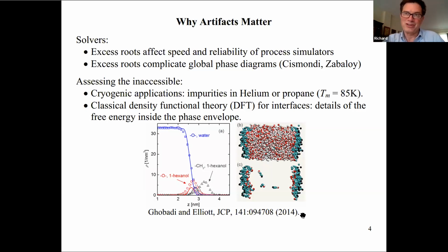So their SAFT-VR models are all for tangent spheres. So you might assume that their theory only works for tangent spheres, but the SAFT gamma originally conceived was actually, the whole reason for it was because it could treat fused spheres. And so that's what we liked about it. So you have an extra parameter in there and a way to adjust things so that you can use that equation of state approach to represent your real molecules.